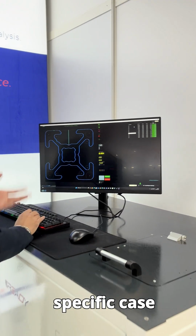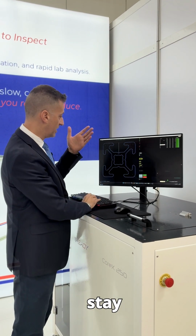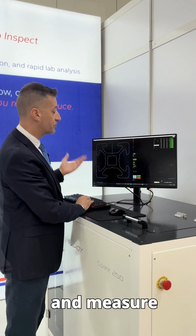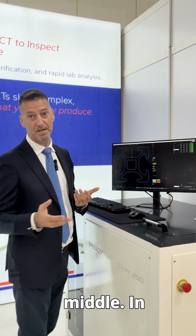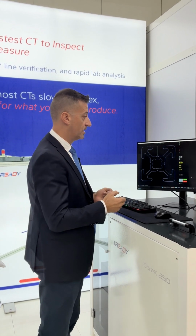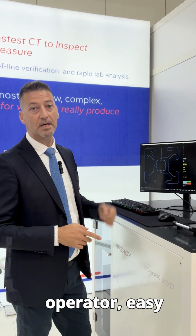And in the specific case of an aluminum profile, it's very difficult to cut properly, to stay perpendicular to the axis, to avoid burrs, and measure this on an optical measuring machine. In this case, you just cut the element, you put in the machine, and we measure in the middle. In this way, it's much easier, you save a lot of time. That's our goal. In the shop floor, with the operator, easy to use.